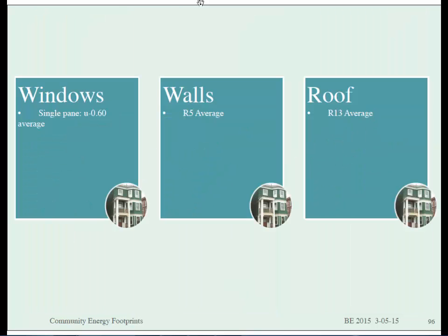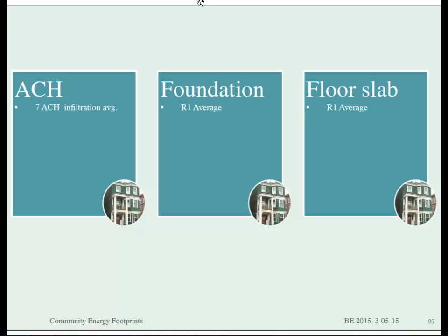Once all that can be gleaned from public record is taken, we look to field research done on sample groups of each home typology. So the idea being that after you've looked at 100 triple deckers, some things become evident: every time you see this pattern of thermal bypasses that are germane to that type, this type of boiler can be expected. First floor typically will have ducting because it's easy to get to from the basement, and so on. And so a picture begins to take shape as we build the home's components.